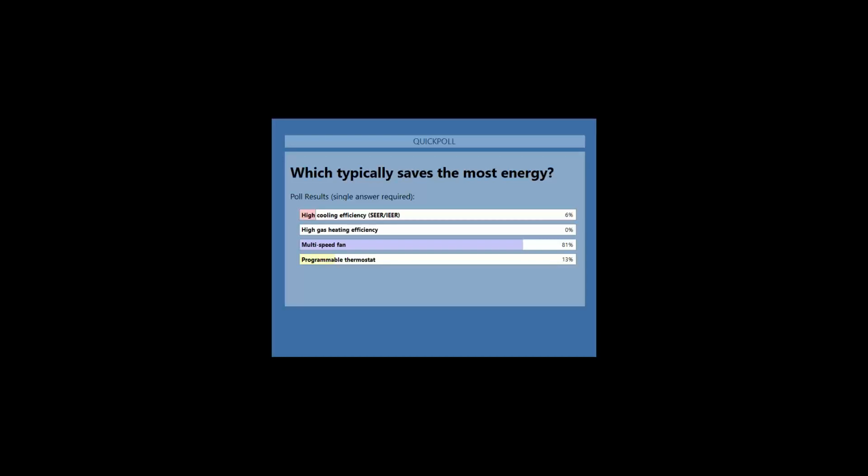First thing is we've got to recognize that we don't need all the capacity all the time. We talked about this on the first webinar. There's very few hours that you need all the stages, right? So for Southern Wisconsin, our design days are like 87, 88, 89 degrees, somewhere where my red dot is here. There's very few hours of the year on a rolling 30-year basis that I'm actually above 90 degrees. It's really small. So I don't really want to design my system for that. I want to design for the 87, 89 degree day. And you can see from an energy standpoint, if I can do an awesome job of saving energy in here for cooling, I don't really care if I waste energy on some freaky 90 degree day, because I want to save it all these hours of the day.